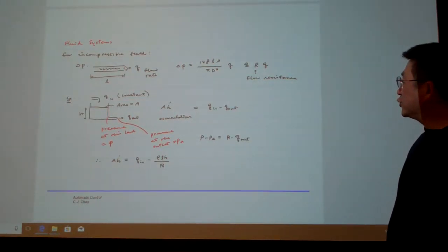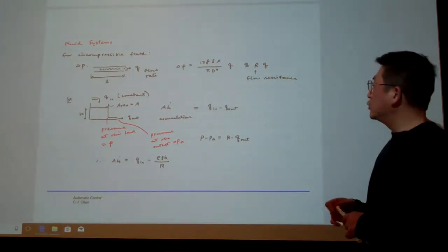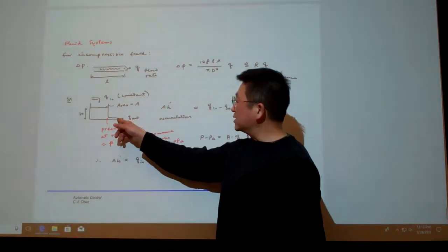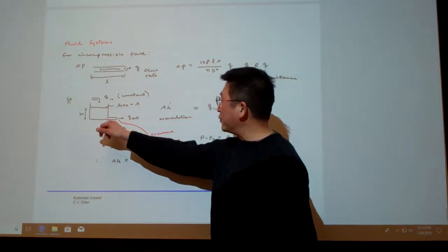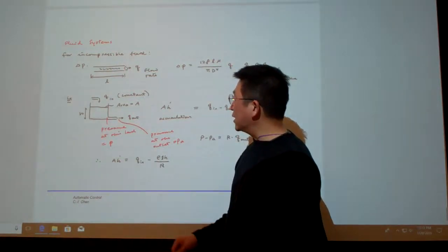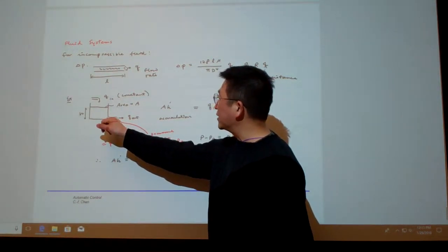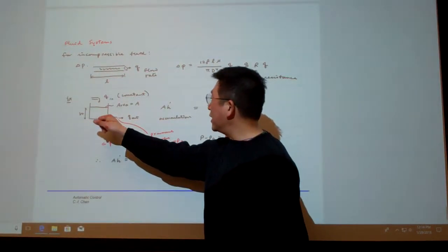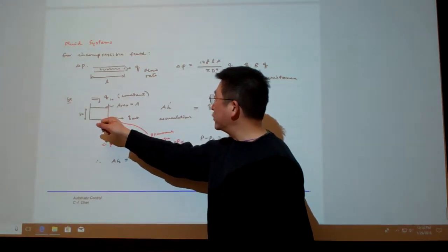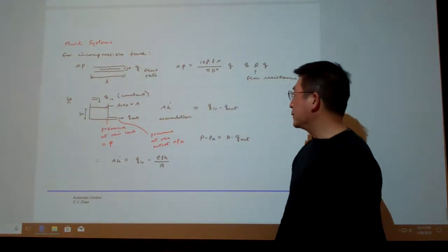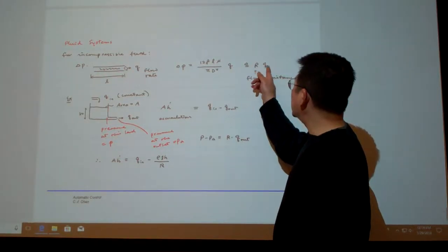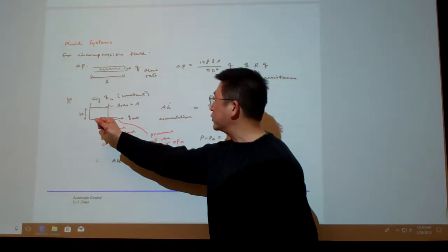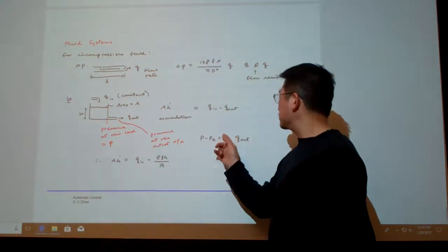Now we can determine how to determine the output rate here. And the output rate, the discharge rate here, basically is governed by this kind of distance. Okay, assuming we know the dimension here and we can calculate this coefficient, let me just call it R. So R is the resistance coefficient for this portion. We simply name it R. And that one, per this equation, R times Q equal to delta P. So that means the pressure difference between the 2 points equal to this term here.